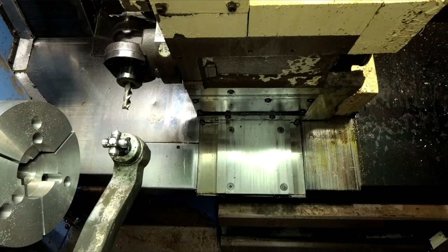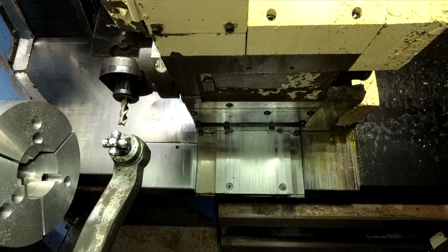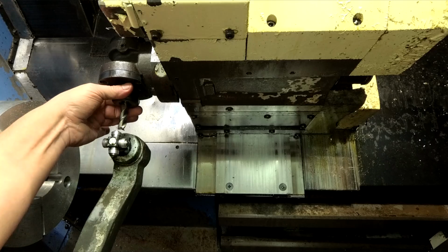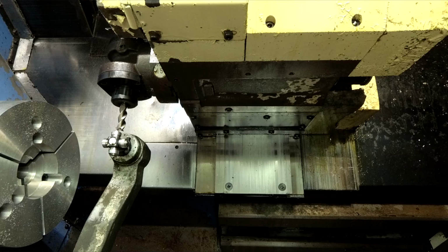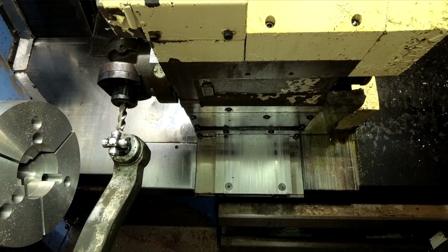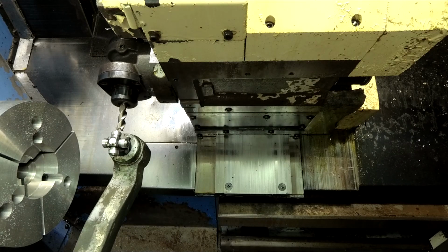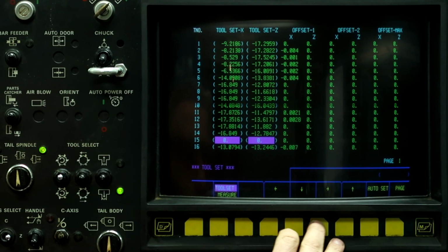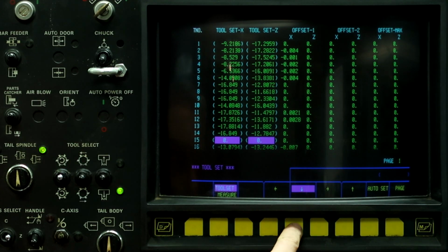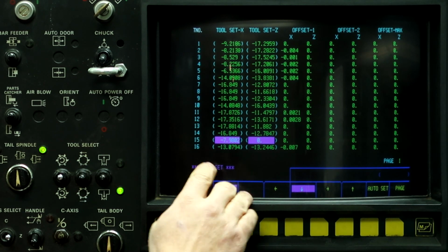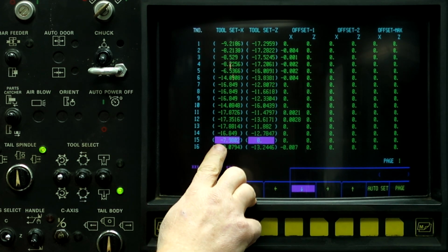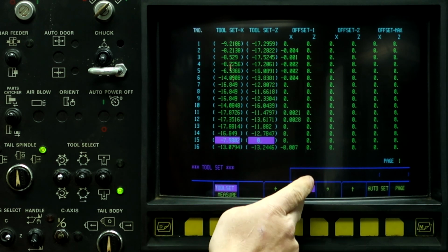So bring it over, we're going to probe X, and then rotate the tool until one of the corners is on the tool. Push the down arrow button and then jog it in a downward direction. So we got the beep, here's our X position. Turn off the arrow,